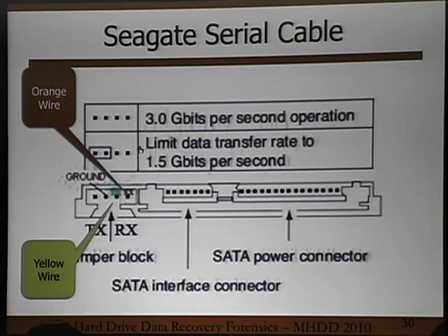But ultimately, these pins over here that most people didn't even know would normally set your speed, which are usually set, by the way, to a default of limit my transfer rate to 1.5 gigabit. Not that you have a controller that can do this anyway, so it doesn't really matter, or a drive that spins that does this, unless you have solid state. But most of you didn't even know you probably had a jumper there that set that to 3 gigabit versus 1.5 gigabit. Anyway, that's what that jumper is. You hook up these two wires, the orange wire from that list and the yellow wire, and you plug this into a terminal. And you will be able to tell almost all diagnostics problems with Seagates.